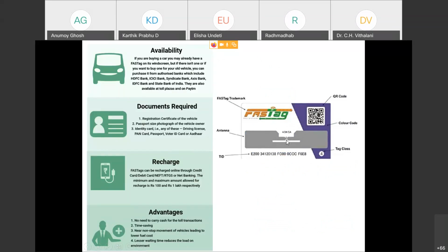If you look minutely, within the gap there are two protruding arms. One is going up and another is going down. These are compensating the inductive impedance of the chipset. This is a capacitive loading, because in general the chipset which is introduced in a tag has some inductive impedance, and these protruding arms are balancing that inductive impedance with that amount of capacitive impedance.